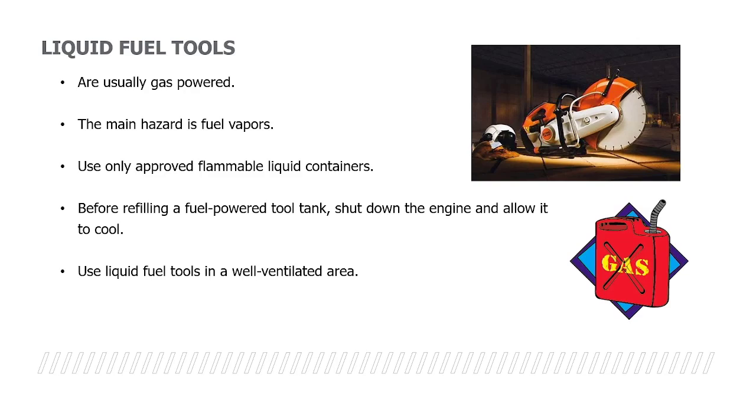Use liquid fuel tools in a well-ventilated area. If you happen to be working with liquid fuel tools, they do produce carbon monoxide. You can't see it, smell it, or taste it. That's why these type of tools need to be used in what type of an environment? Outside in an open area or an area where there's ample ventilation flowing through that particular location. So remember that about liquid fuel tools.